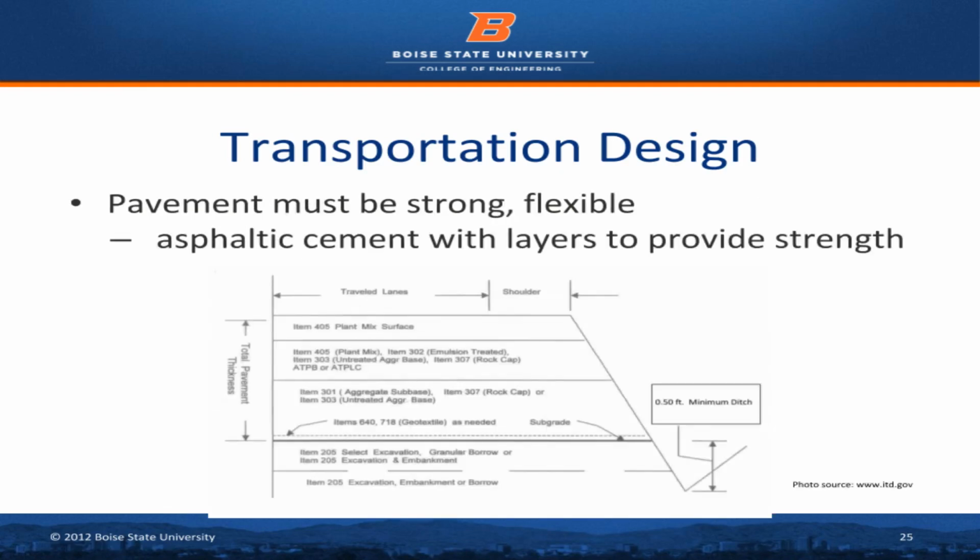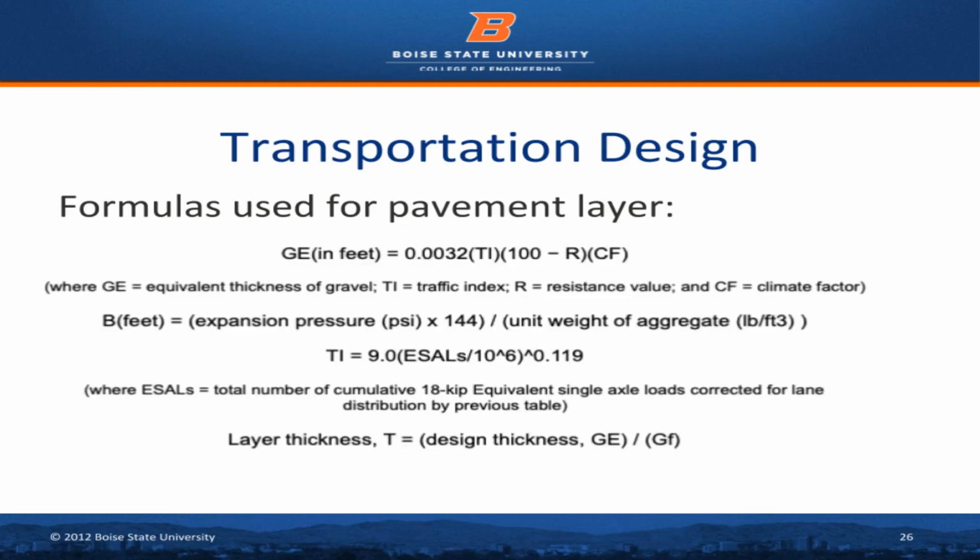It's pretty obvious that since there are going to be many heavy trucks, the pavement of the parking and driveway areas must be very strong and flexible. The type of pavement selected for this site is a flexible pavement. As you can see from the diagram, there are different layers which each have a specific purpose. I used several formulas when calculating the pavement design. I was able to determine the precise requirement to construct an effective parking area.